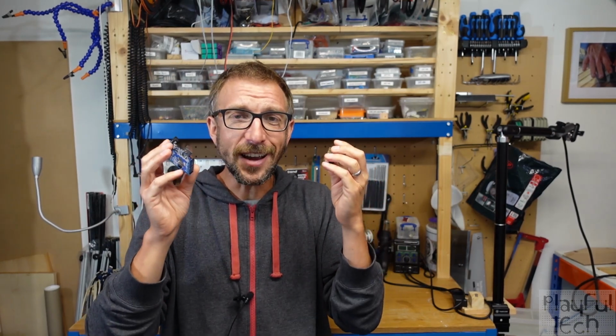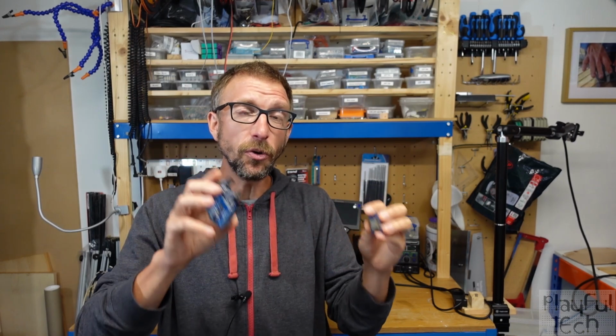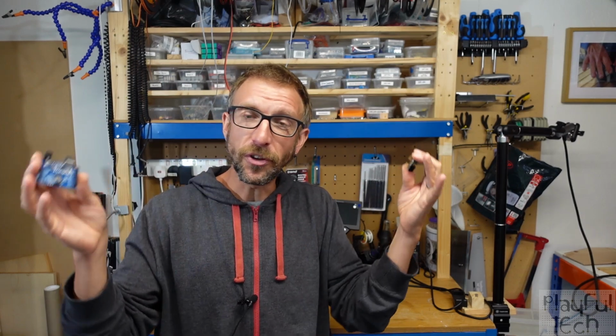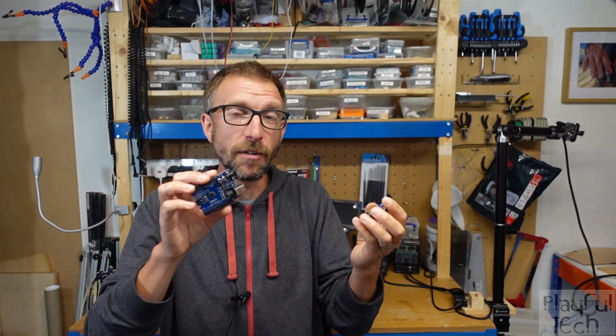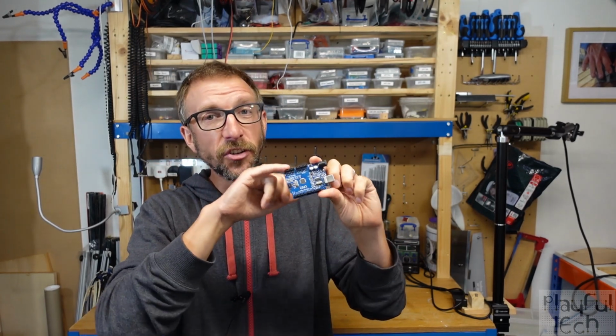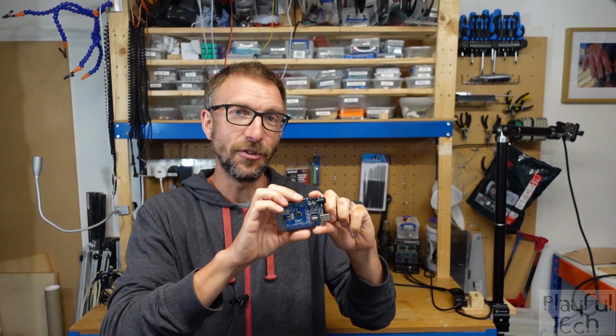And whenever you want to connect an external device to a GPIO pin, you generally also want to connect the ground pins from the device to the processor to create what's called a shared ground. So they've all got this common point of reference. It's like calibrating them to the same 0 point, which means that they can then agree on whether the signal at the GPIO pin is high or low compared to that ground.